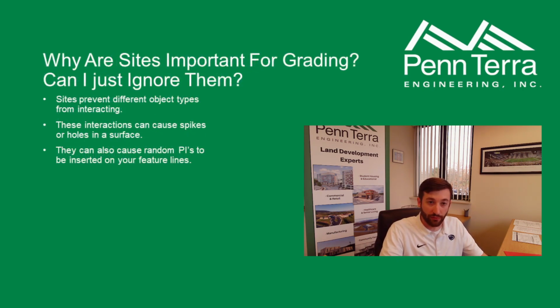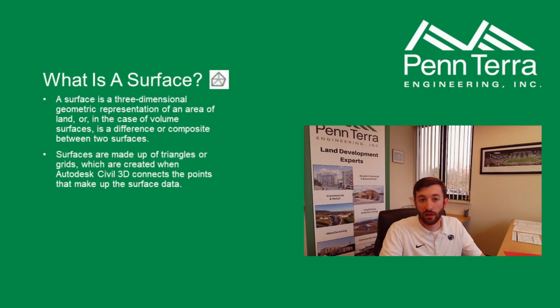Why are sites important for grading? Again, they're going to prevent objects from interacting, adding extra PIs to feature lines, messing up labels on parcels, putting big spikes or holes in a surface, those types of things.